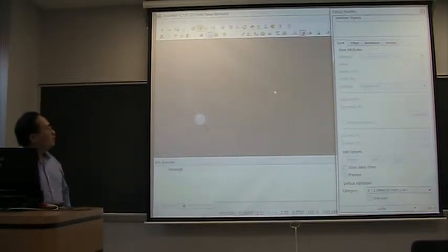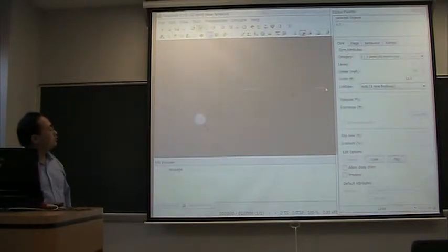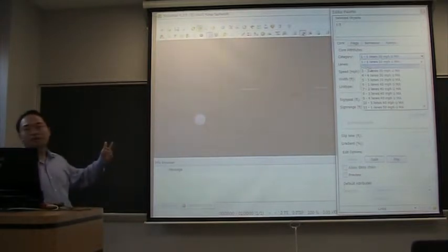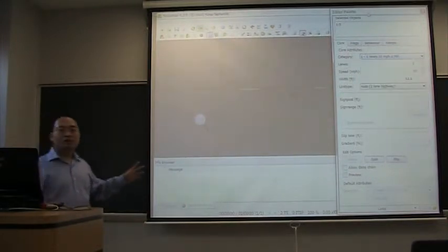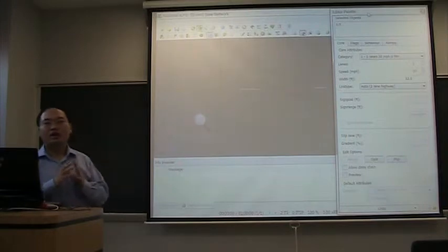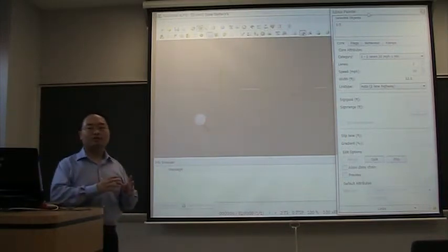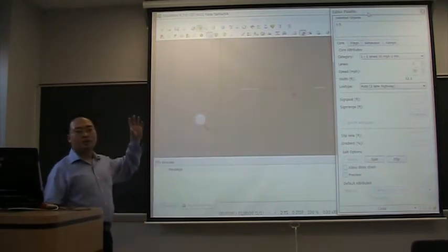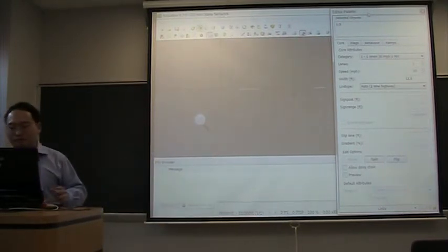Now if we select one link by using the middle button and right button, we'll be able to see the selected object here, and I can specify the category of this link, meaning how many lanes and the speed limit. In Parametrics, each link belongs to a certain category, and you define the category. You change the speed limit or the number of lanes by defining new categories. So it's organized.